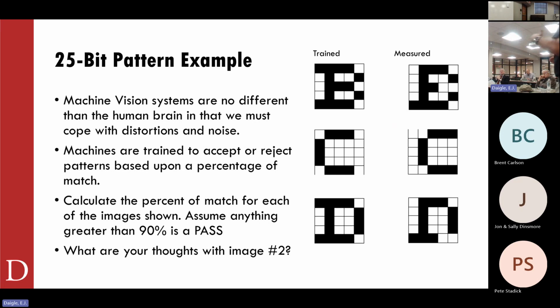You've calibrated the system to a certain amount of ambient light. So what you'll see out in the real world is people will smoke out the windows. They'll put a dark tint on all the windows of the cell. The machine vision system will go inside and they'll illuminate that cell from inside so that the ambient light is not part of that. We call that a doghouse in the world of machine vision. We hide all the ambient light and then we control our light from the inside. We can control the angle the light is coming in from. We can control the type of light and exactly what the light is.